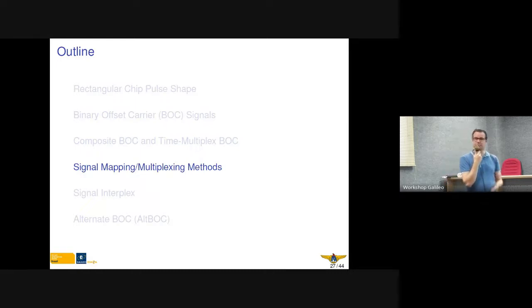There are a few papers already available discussing this for GNSS, but the majority of this work was done many years ago for communication systems, which are definitely only interference limited. The noise is playing a minor role in communication systems where you have hundreds of users using the same frequency band.